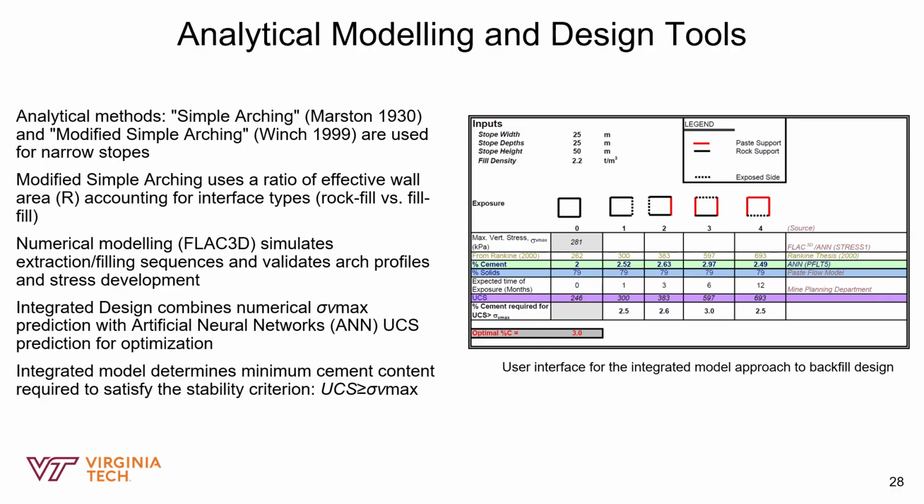So for more complex geometries, simple equations aren't enough. So we use numerical modeling tools like FLAC 3D. These simulations allow us to model the entire extraction and filling sequence over time, and that validates exactly how the stress arch develops.